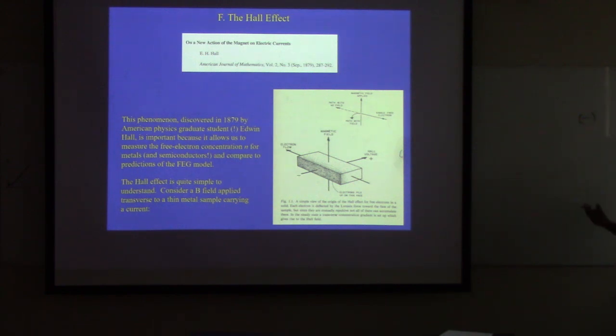But if you have a semiconductor, we are going to talk later, there are intrinsic semiconductors, which have electrons and holes. Intrinsic means they have the same number of holes and electrons, but we can purposely do something called doping. We can put in more holes to make a p-type material, or we can put in more negative charges to make an n-type material.